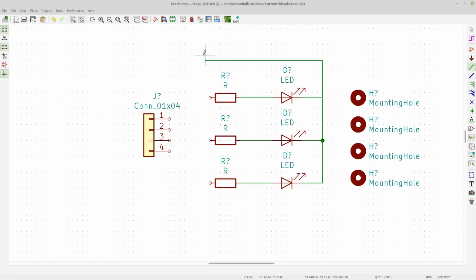And then I'm going to go around, and I'm going to come down. Let's go over a little bit more, and I'm going to come down to pin 1. So pin 1 is going to be lined up with ground on my Arduino. So that's why I'm orienting it this way. And now I'm going to do the resistors. I'll do this easy one first, and then I'll do this one. So I just try to make it look pretty. We'll fix that in a second.